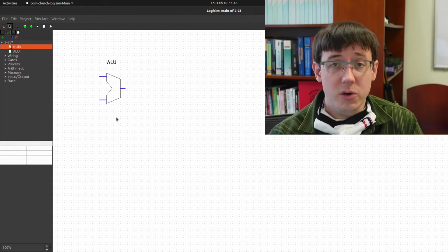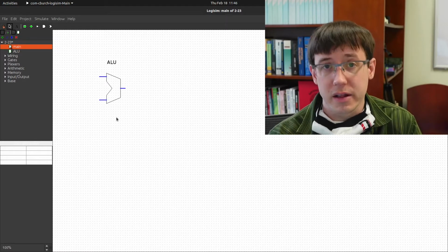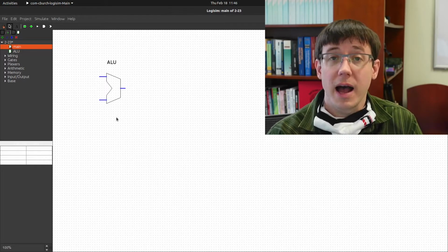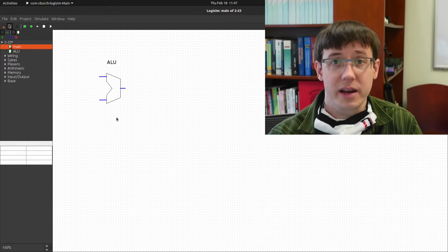Today's other video goes into much more detail on some of the arithmetic and logic components that are part of the ALU. So in this video, I want to focus on how those pieces are put together and how we can simulate that in Logisim.